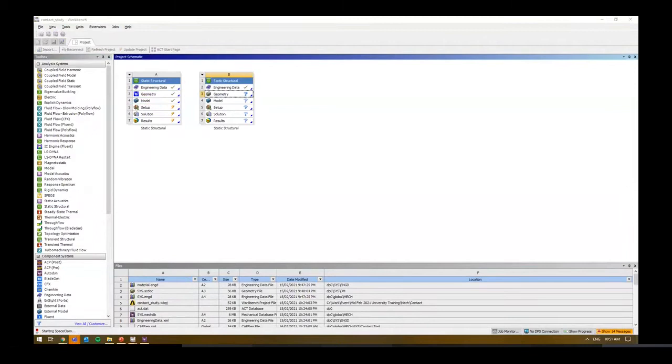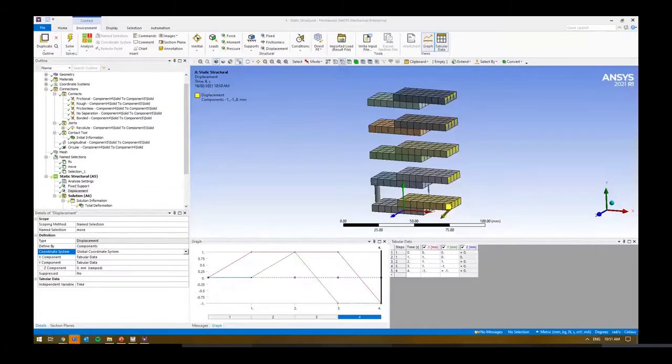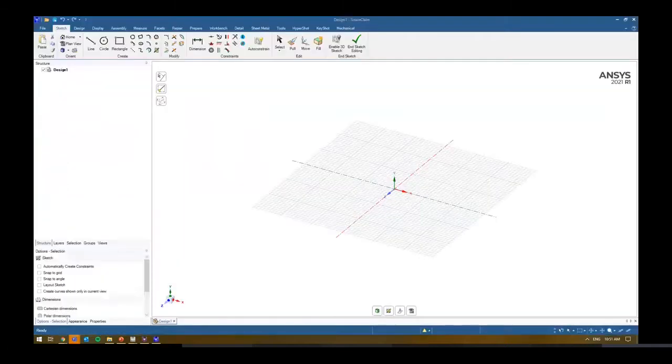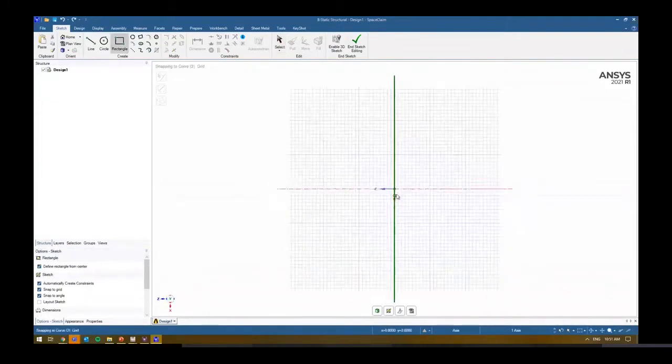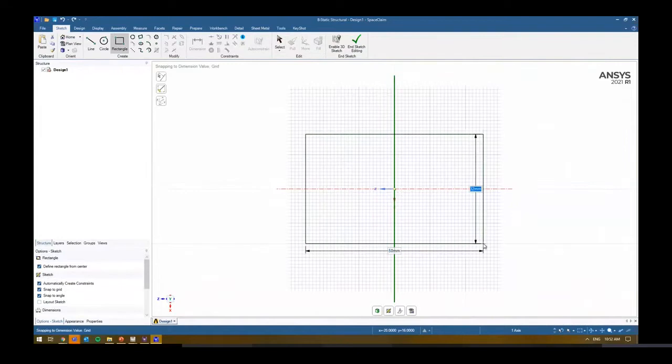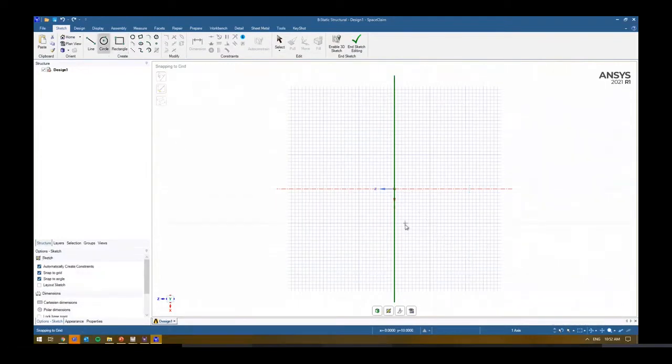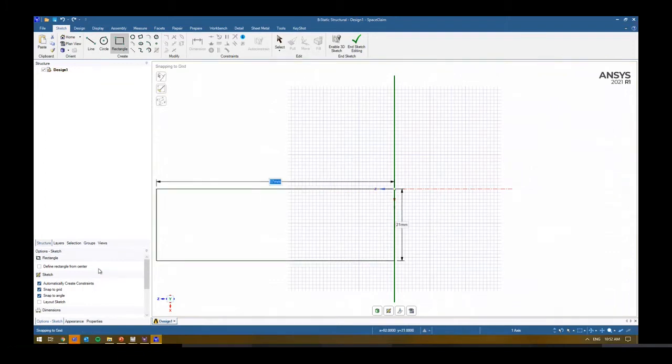So while that's going, motion spring. Does the spring have bending deformation or is it linear movement? It's just linear movement. So it's a linear spring. You can specify a non-linear spring, give it different stiffness values. There are some elements in there as well that can have tension-only springs, depending on what you're after. But this is just a 1D kind of element. So if you've got a non-linear spring in bending, you might want to reconsider using that element and use something else. So let's just make this 50 by 50. Let's go back to 50 by 50.